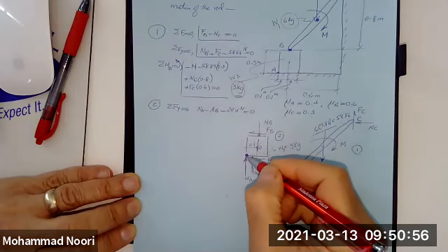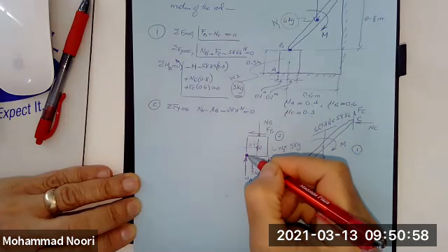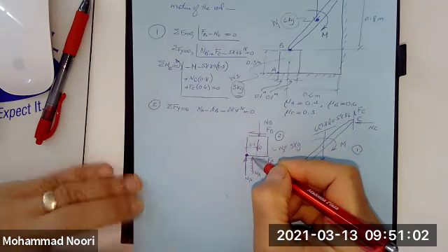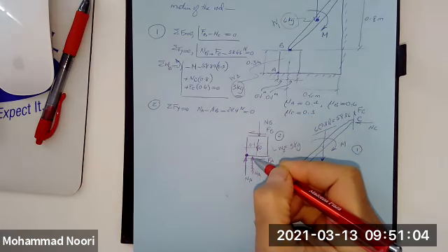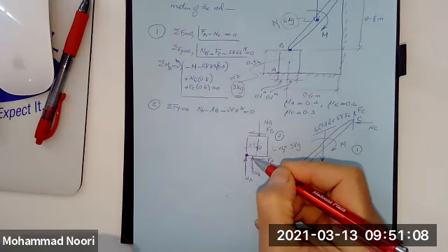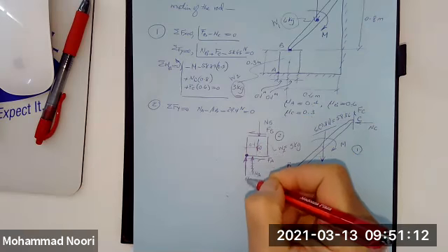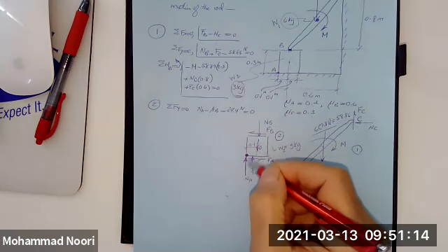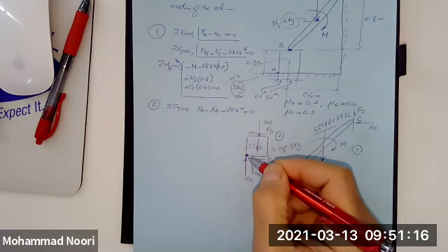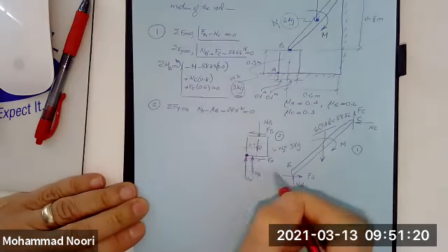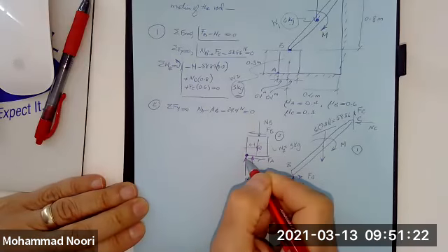Since this is a point where the block is at the point of pending motion, that's where it is really touching the ground, the reaction force would be at that point from the ground. It's almost like a roller here, except that the roller also has friction force.